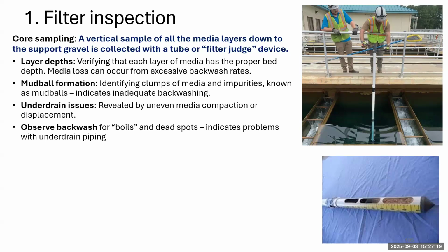You also want to observe the filter during backwash. If there are places where there are boils, like boiling water, there's too much water coming out there. And if there's no action at all, it means there's a dead spot. There could be broken piping or blocked piping.